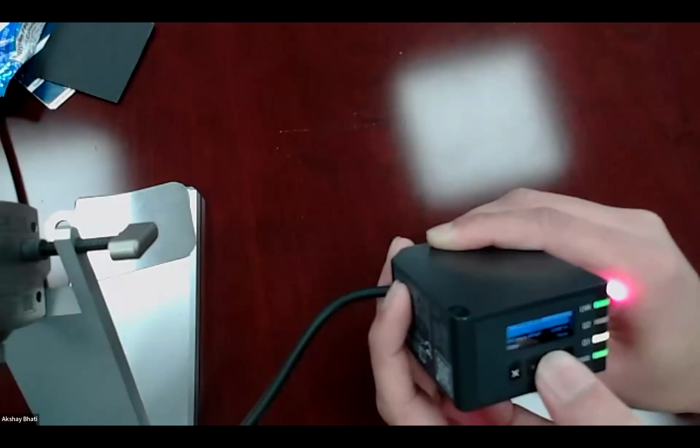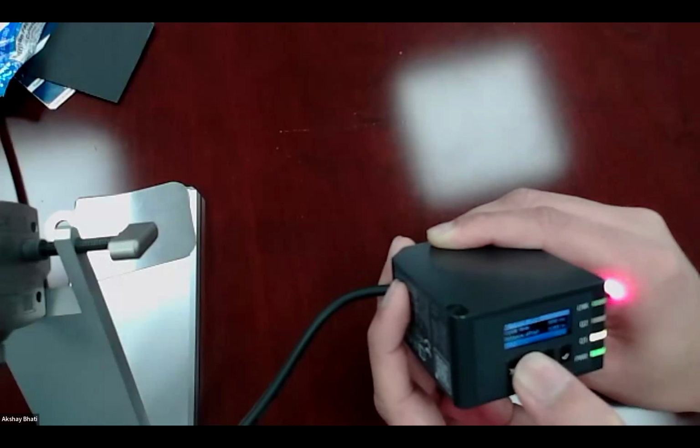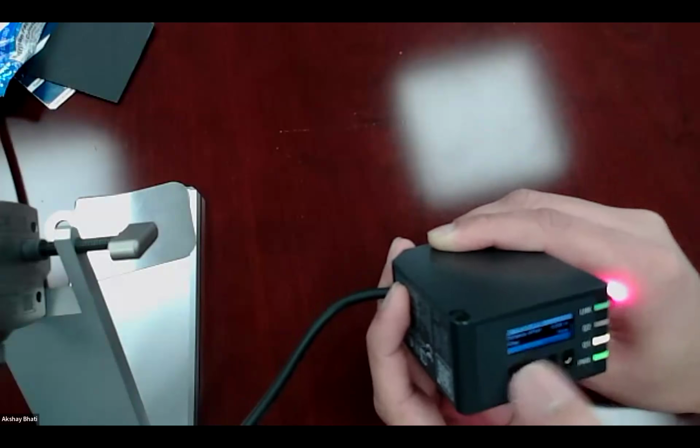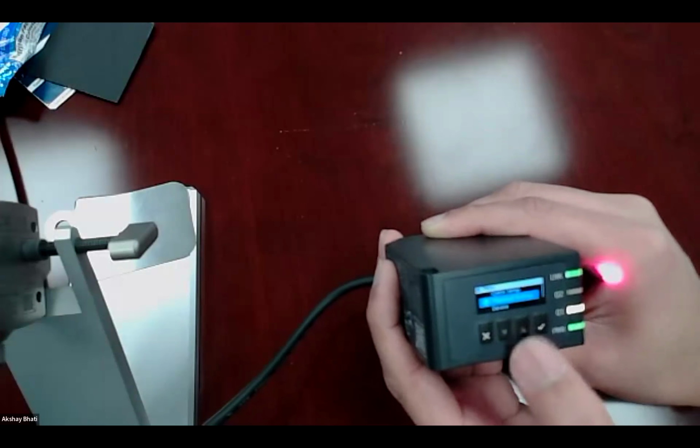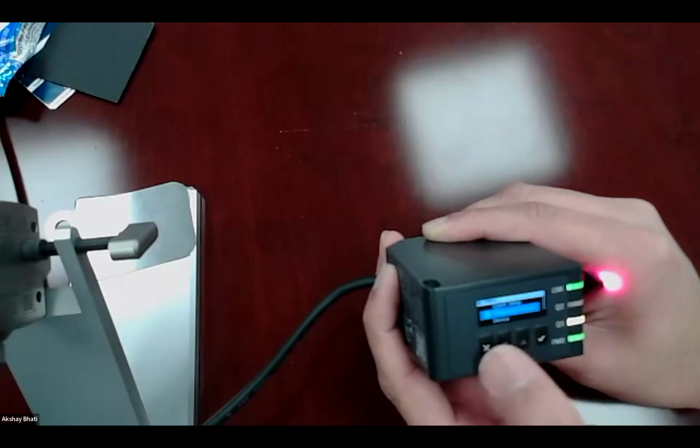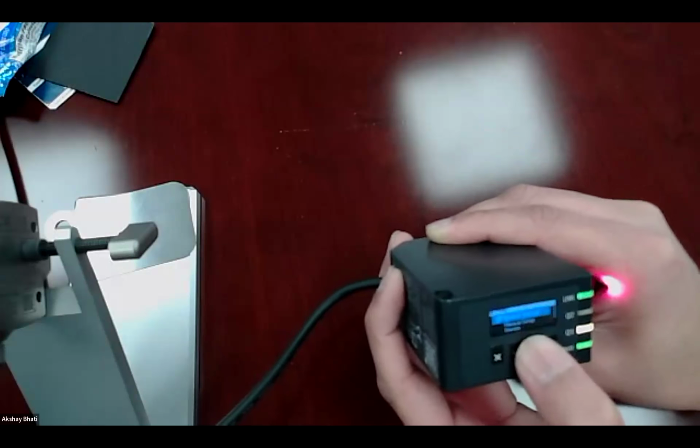Then the next one, after we select the mode, we can do the manual setup. This is where we select the cycle time manually, like what cycle time we need, and filters. Let's say if we have variable readings, then we can have something called average filter to get the average readout from the target and things like that.